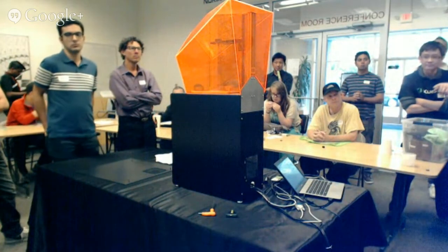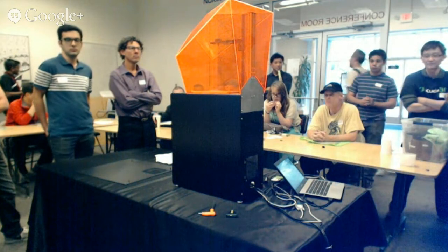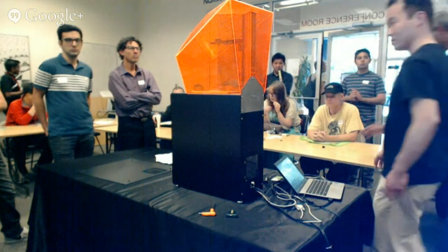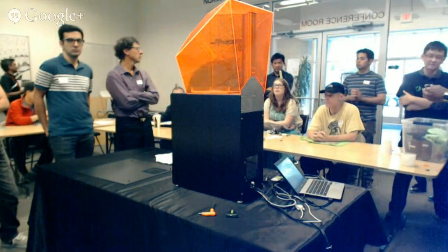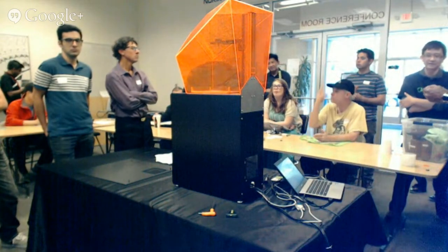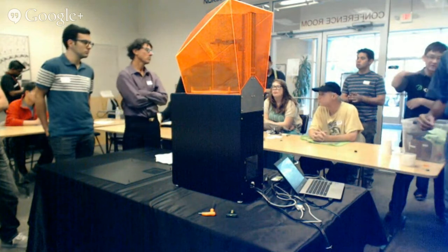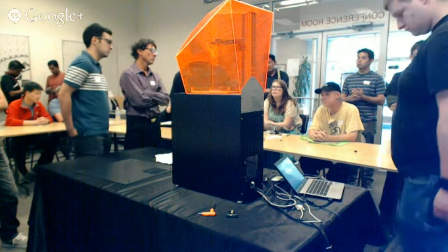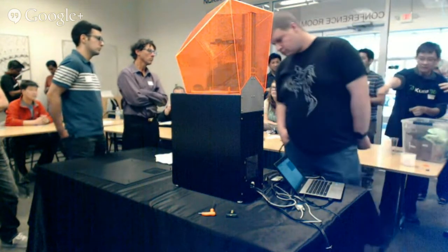But if you did this at thicker layers, then it will be less of this effect, or no? It got through 4 millimeters. That post is 4 millimeters tall. So I cannot do anything about this problem with a part like this, except by changing my design so that I don't have those types of features, or by adding some type of blocker, something chemical, into the resin. I can't do anything about that in settings.